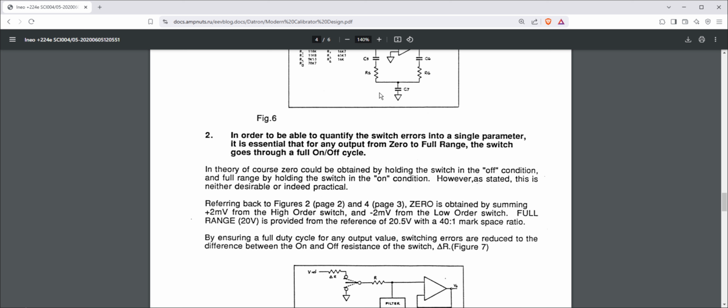A PWM DAC is not supposed to be run at 0 and 100% duty cycles, that is, neither throw should be turned on continuously. After sacrificing the endpoints, the INL is finally down to the level of the 85791, and I'm not sure how much of it is coming from my Keithley 2000. So to find out, I'll quickly package the board and send it off to be tested under the watchful eye of the HP3458A. The results speak for themselves.